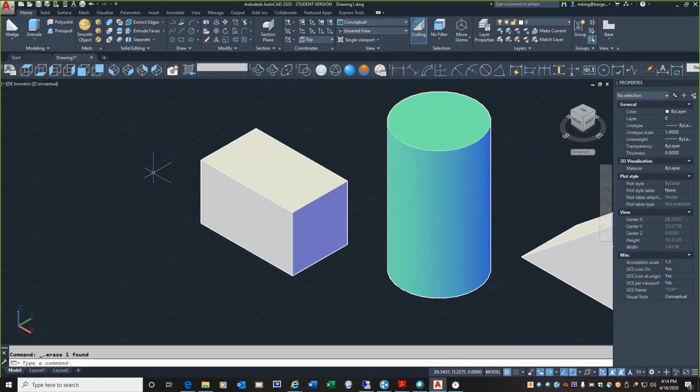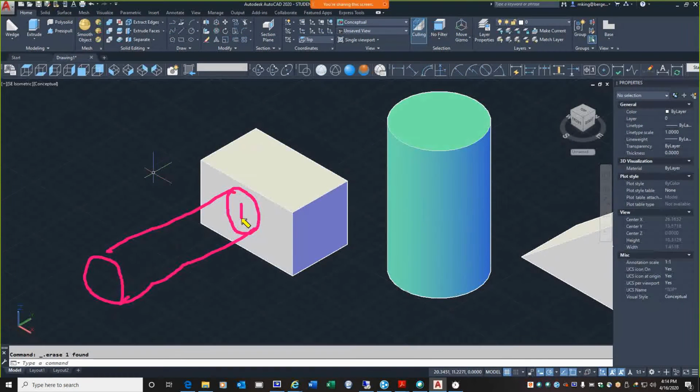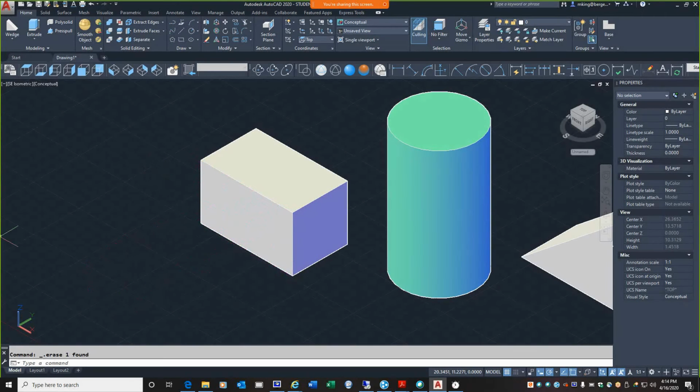Now, let's say that I want to create a cylinder that is affixed to the side of this, and it's going to grow outward, okay? And I need the center of this cylinder to be in the center of the face of this box. So that's my requirements, and as far as the size and the length of that, we'll talk about in a second. All right, we need to do something to our UCS first before we can proceed, because there's a mode that's on right now that is going to fight what we want to do. It's like having all your O snaps on and trying to get somewhere. It just becomes less productive.